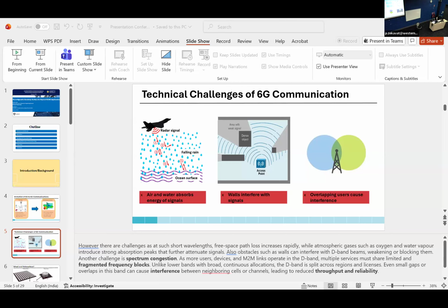So this study presents a polarization independent reconfigurable metasurface using PIN diodes, and the design uses two layers. The top layer is a lossy layer made of square loop with resistors and PIN diodes, and then the bottom is a frequency selective surface enabling signal transmission. So when the diodes are off, the structure acts as a frequency selective rasorber, providing a transmission window at 4.28 gigahertz.